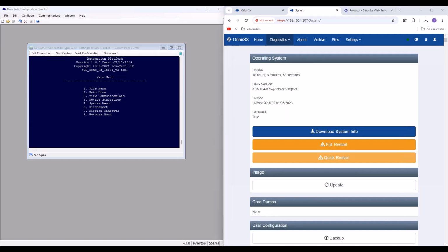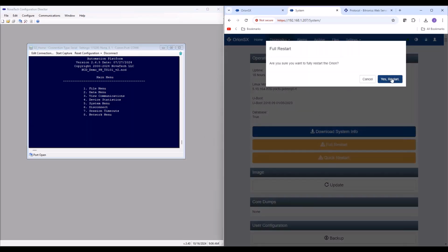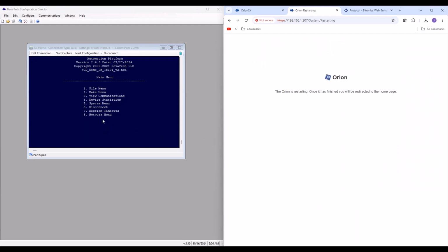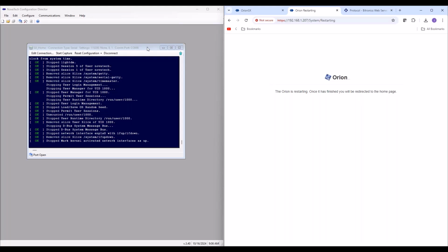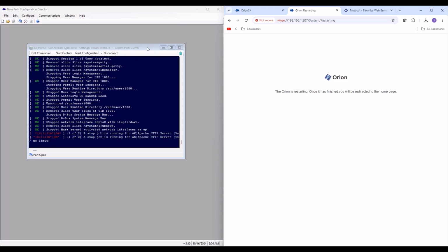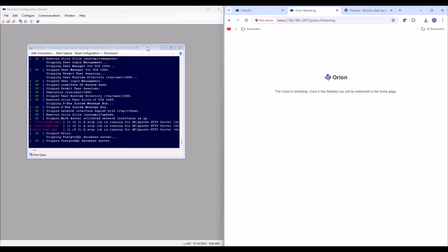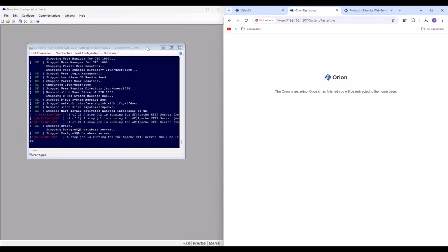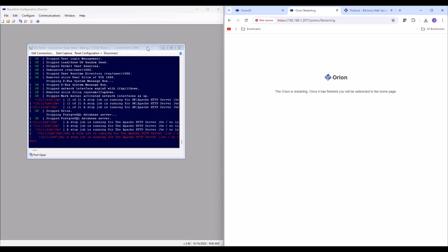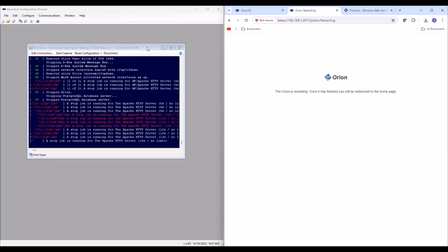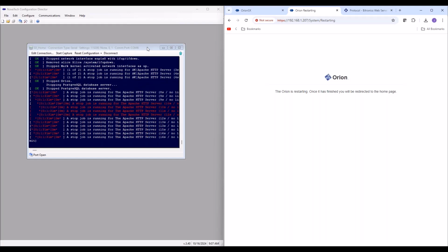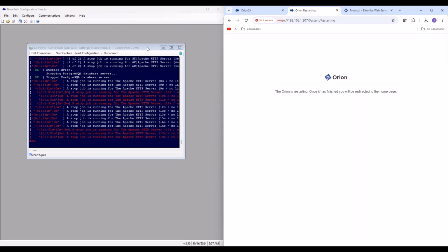The process takes maybe 2 or 3 minutes, but this is the key thing here, you really have to watch the boot sequence on your MMI. Near the end, it'll present you with an option, and it'll ask you, do you want to wipe your user data? And you have to type in yes and hit enter, and it'll ask you to confirm that decision, and you'll have to type in yes a second time and hit enter.